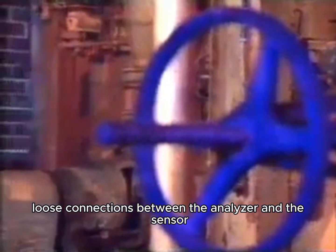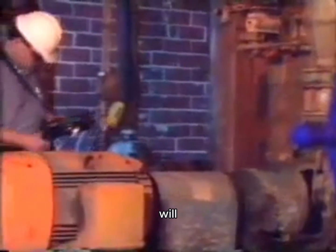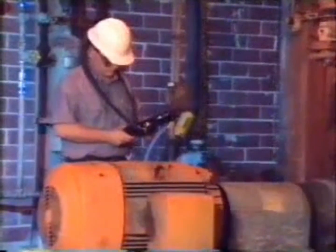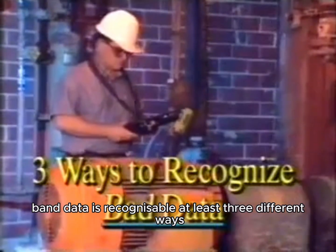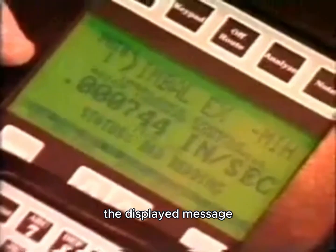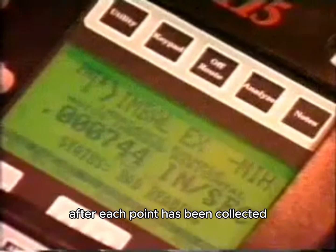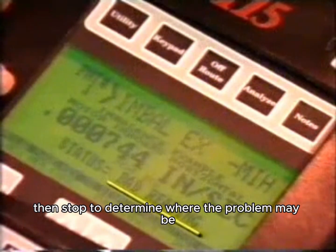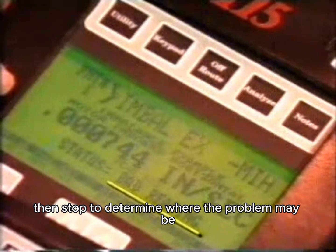Loose connections between the analyzer and the sensor will cause either erroneous data or no data to be collected. Bad data is recognizable at least 3 different ways. The simplest is to pay attention to the displayed message after each point has been collected. If the message is bad reading, then stop to determine where the problem may be.